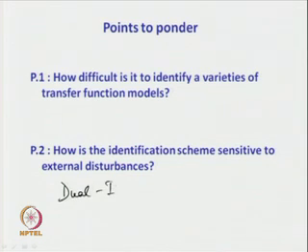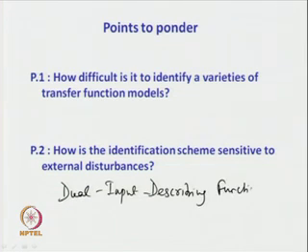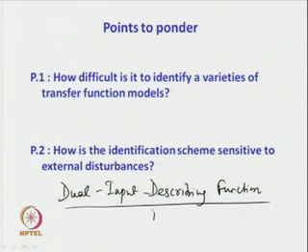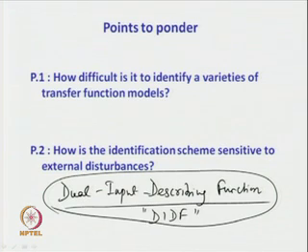Also, it is possible to make use of another analysis technique known as dual input describing function analysis, DIDF analysis, for the relay control system which is subjected to external static load disturbances. In this case, it will be possible to estimate more parameters, and also it might be possible to estimate accurate values for the transfer function model parameters. That is all in this lecture. Thank you.